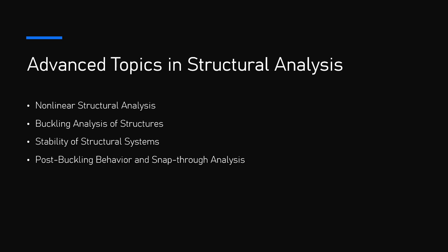10.4. Stability of specific structural systems. 1. Structural frames. Frame structures are generally designed to resist both vertical and lateral loads. Stability analysis of frames must account for P-delta effects, the effect of lateral displacements on the axial loads in the frame members.